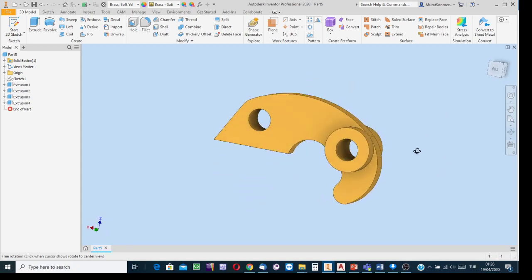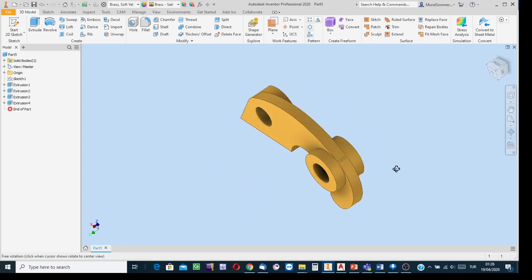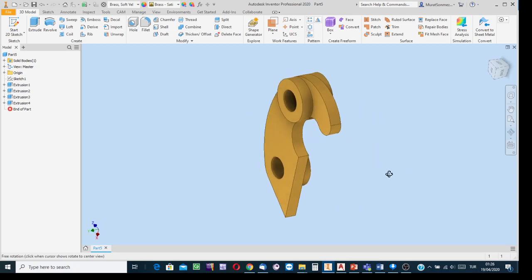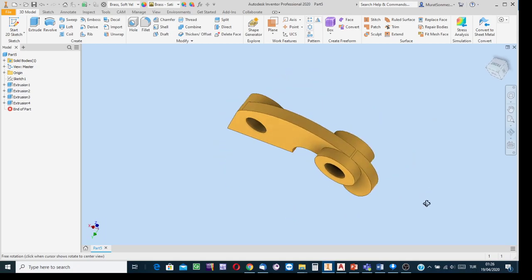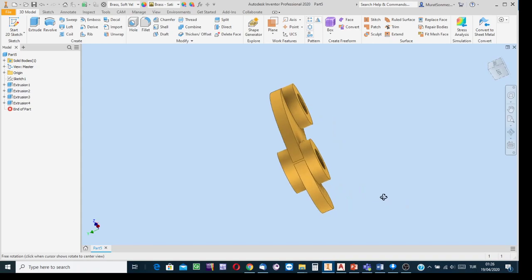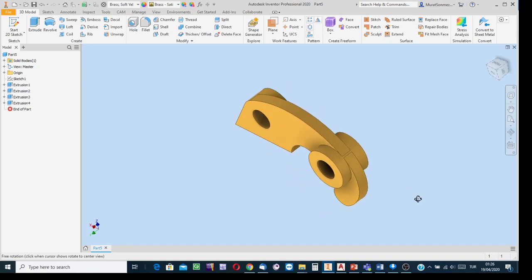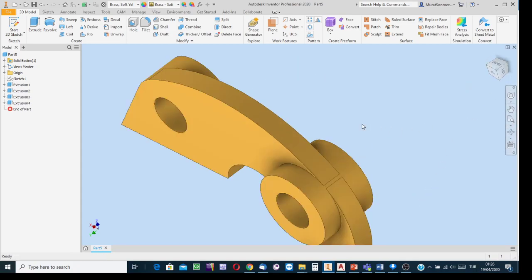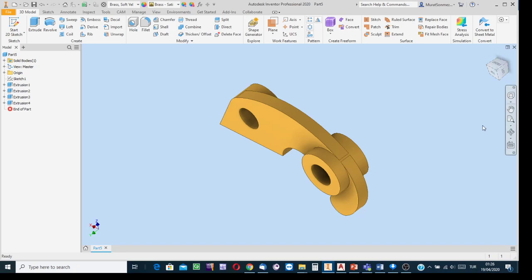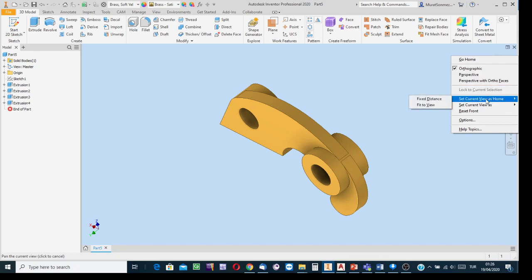Use the orbit facility to allow the other person to see the model of the object from any direction. And if you want, when you click on the cutter symbol, to see the model oriented like this, then after positioning it like that using the orbit facility, bring the cursor on the cutter symbol, right click the mouse and say home positioning.